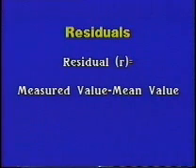Our next step is to determine the precision of the set of measurements. To determine the precision, we must first determine the residual for the 12 individual measurements. A residual is defined as the difference between the value of each individual measurement and the mean of all the measurements, as shown by the formula. Residuals are theoretically identical to errors, except that the residual can be calculated and errors cannot. Take time now to determine the residual for each measurement in our example and note them in the column under the small r.